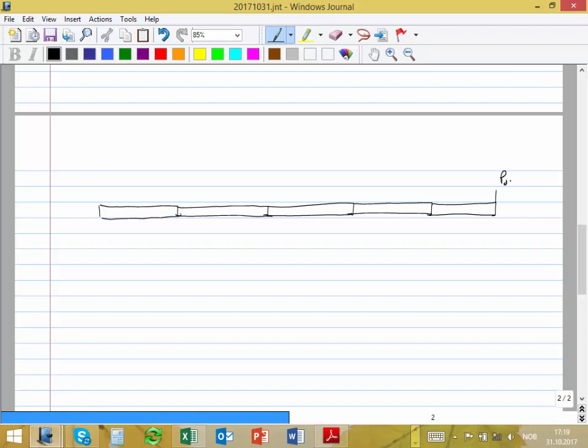Okay, I have here P separator, that is 50. And what I'm going to do is calculate the pressure. Let's say that this is pressure 1, 2, 3, 4, pressure 5. Pressure 5 will be equal to the pressure of the separator plus the delta P that I calculate in this point, times the gradient.